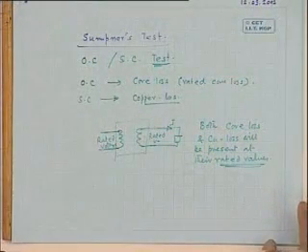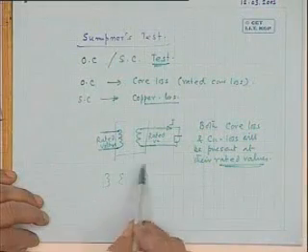Therefore, although the open circuit and short circuit tests are important because you can find out the equivalent circuit parameters, by doing these two tests separately you really do not know how the transformer will operate when it is fully loaded. So, one way out is to operate the transformer in the laboratory at full load condition. You do the open circuit test, the short circuit test, and also a load test.